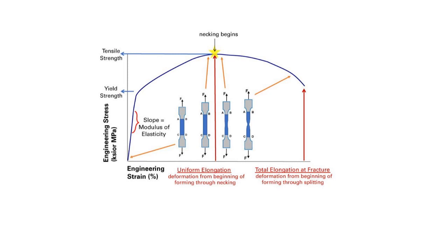First, we have to prepare the specimen. Then the specimen is placed on the UTM. The extensometer is placed, and the reading is set as 0. Load is applied slowly and the neck will be formed. Load is applied to the specimen. The neck formation, we can see in this diagram.